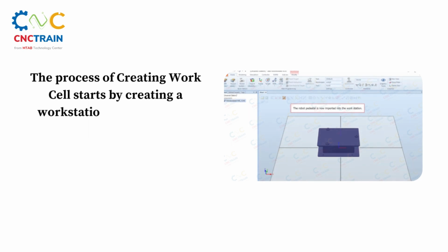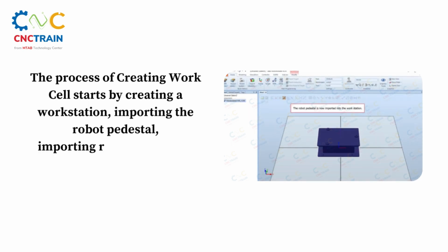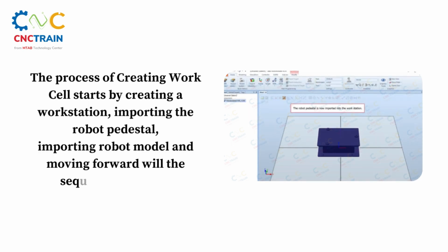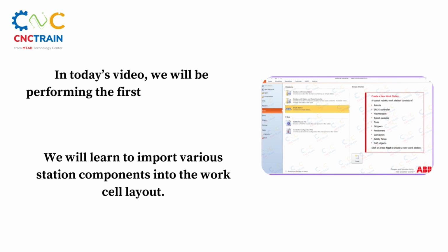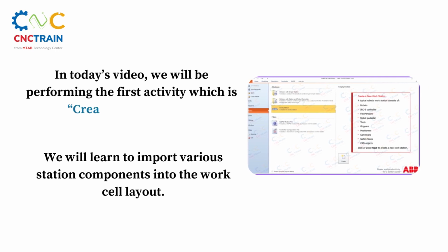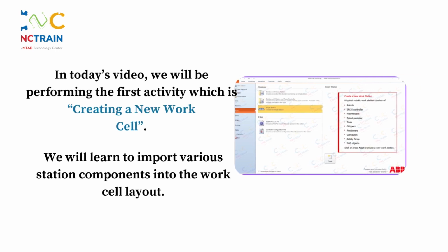The process of creating a workcell starts by creating a workstation, importing the robot pedestal, importing the robot model, and moving forward with the sequential process. In today's video, we will be performing the first activity, which is creating a new workcell. We will learn to import various station components into the workcell layout.